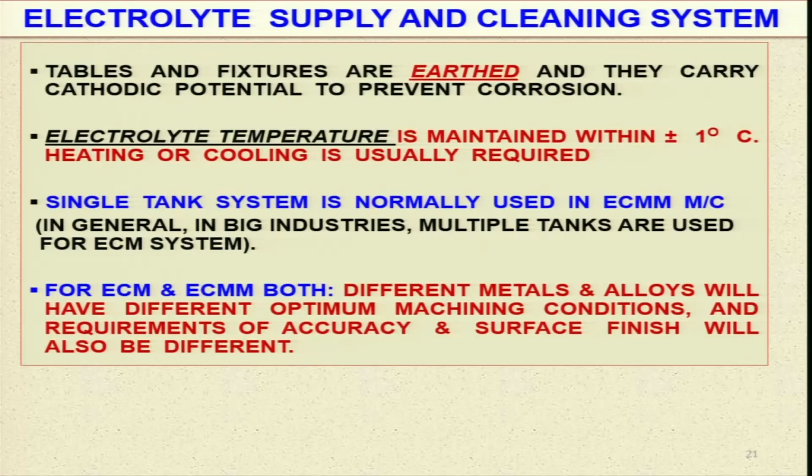For ECM and ECMM, both different metals and alloys will have different optimum machining conditions. This is very important, optimization of the machining conditions before really machining a part in the industries, and requirements of accuracy and surface finish will also be different.